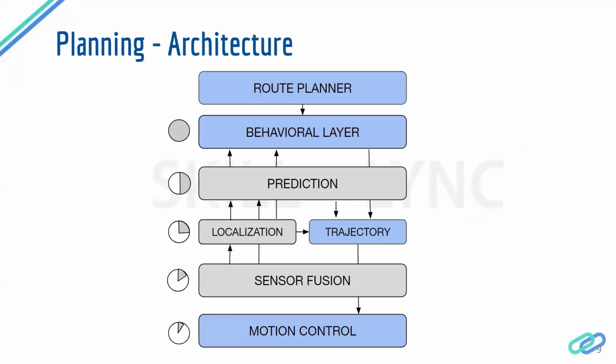module is operating. So generally the motion control is the fastest module. It is operating at around 100 Hertz. This is making decisions every 10 milliseconds or even sometimes 1 millisecond, because the control has to be very precise. It should be very comfortable. So if you get into an autonomous car, you should not feel that you're thrown around everywhere. The drive should be very smooth and so on. So this is the motion control, which is responsible for that, and it's operating at a very high frequency.